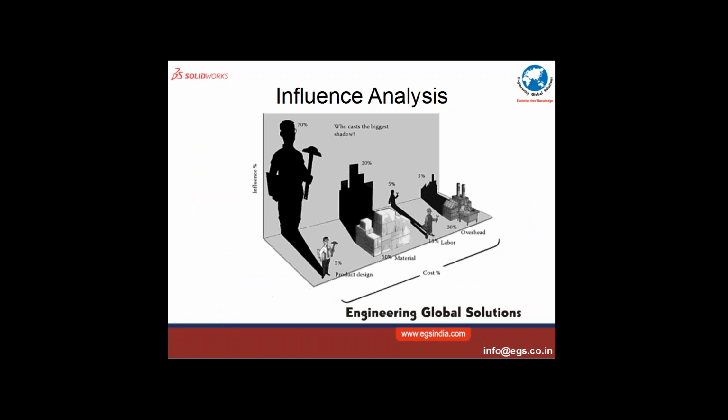If we look at the influence of each and every input that comes in product development, starting with design, selection of materials, labor, overhead costs, and so on, if we look at these primary factors that influence the cost, we see that 70% of the influence on the cost comes from product design. 50% is the material cost, 20% is its influencing factor. 5% is the influencing factor of labor, and 5% is for the overhead. If we were to come up with a methodology or a mechanism to reduce cost, we need to look at no other place other than design, because a significant influence of 70% or over comes from design.